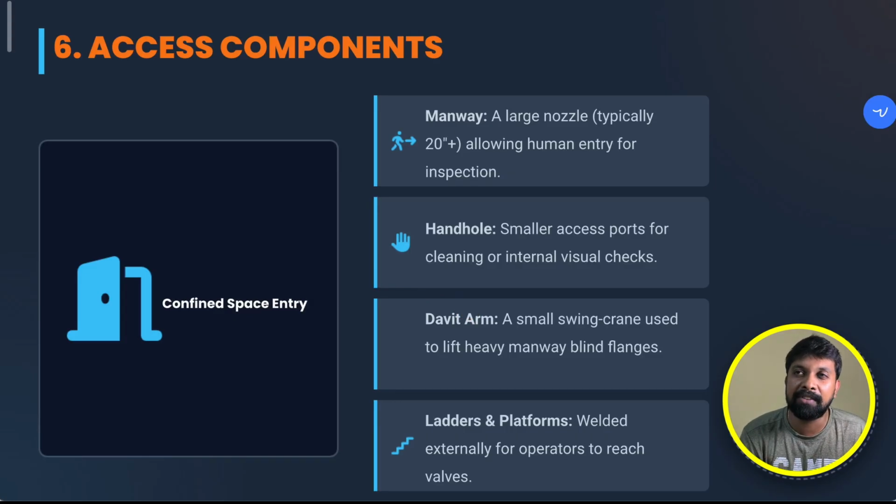In most pressure vessels, it is not common to use a ladder or any platform, but we have ladders and platforms for bigger vessels, which are directly attached to the pressure vessel. If we need to access the manway at the top of the dish, we need to climb to the top of the pressure vessel. For those purposes, we use ladders. And also for large storage vessels, you can see staircases too. It might be a spiral staircase or zigzag staircase, and platforms.